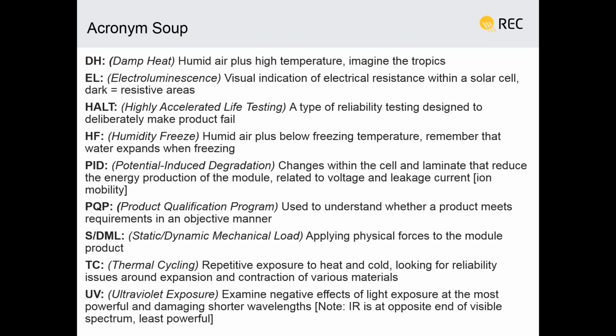Not all of the best practices in PV module reliability drive to failure. Certainly some of the poorer products out there do fail during some of these testing, but the current state of the art is not necessarily to try to push a module to complete failure, because guess what? You can make everything fail. The key is to have tests that reasonably simulate something that is relevant to the real world suite of exposures.